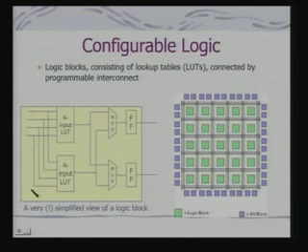So, this forms what is called a basic logic block, which consists in a way of a set of lookup tables connected by a programmable interconnect. In fact, this multiplexer tells you which one is to be connected to the flip flops, and subsequently these blocks themselves can be connected in a programmable way to realize a computation. So, effectively what are we seeing?